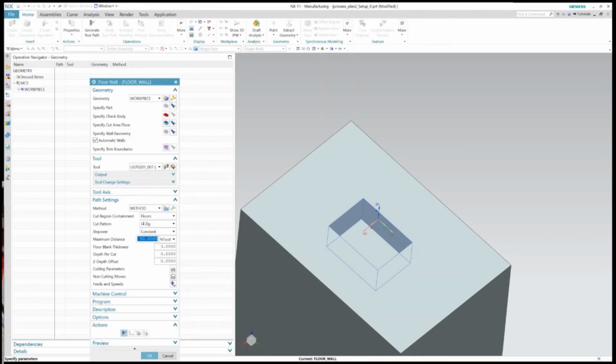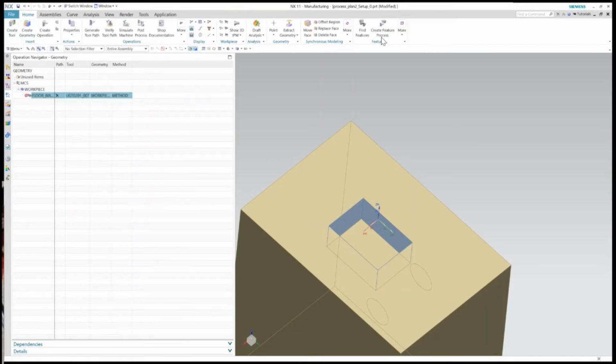And the next thing you want to do is, now I've got an IPW issue, so it won't run. When I tried to run and verify this, it didn't want to because I had an IPW issue, and this IPW issue can be fixed by going back to setup 1 and making sure you update it. So you update the parameters in setup 1 so it can be reflected in setup 2.